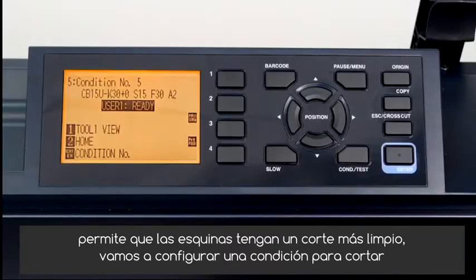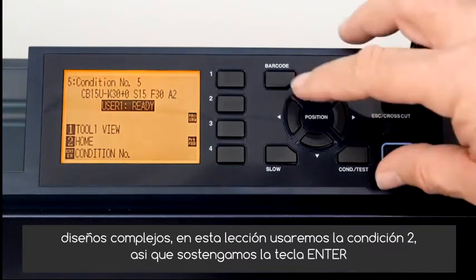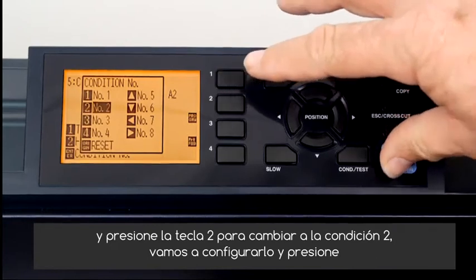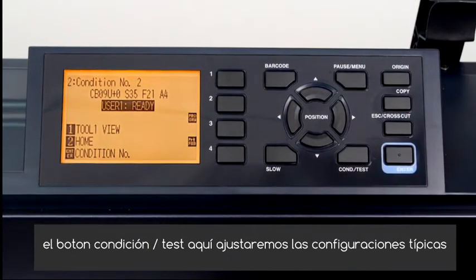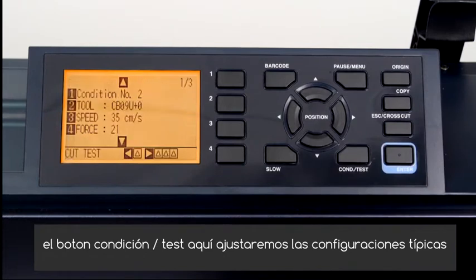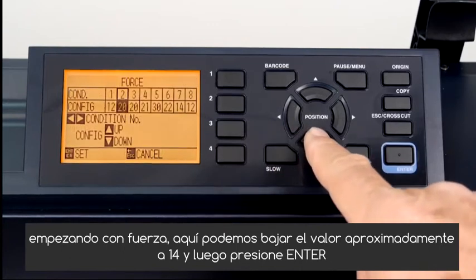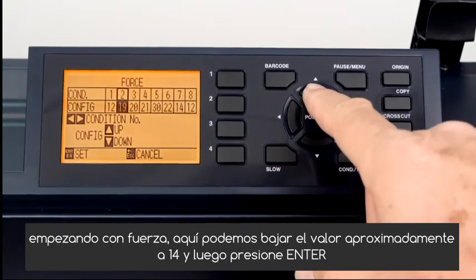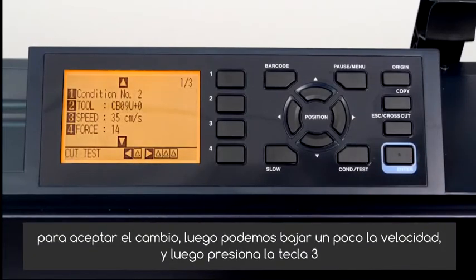Let's configure a condition for cutting intricate designs. In this lesson, we will use condition 2. So let's hold the Enter key and press the 2 key to switch to condition 2. Let's configure it and press the condition test button. Here we'll adjust the typical settings, starting with force. Here we can lower the value to about 14, and then press Enter to accept the change.